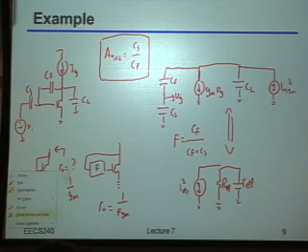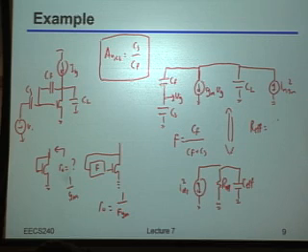Similarly, what's the effective capacitance? So actually, I'll just write this out to be sure it's clear. R effective is just 1 over F times GM. Okay? What's the C effective? What's that equal to? Okay, yeah, so it's just load capacitance, right? That one clearly shows up directly at the output.